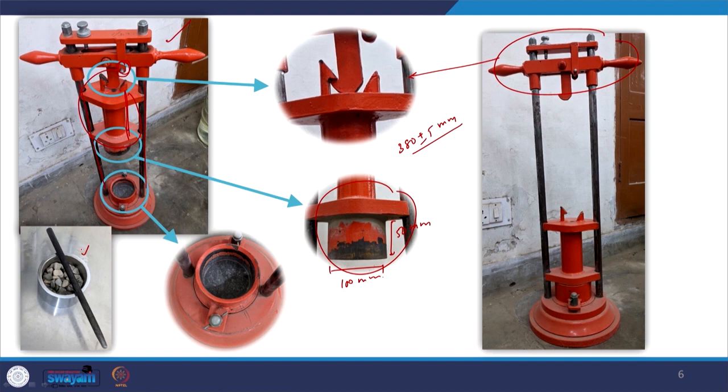The sample measure is 75 mm in dia and it is 50 mm in height, but this sample measure is not directly put in the equipment, alright. This sample measure is used to measure some amount of aggregates, and this aggregate is then placed in the case hardened bottom cylinder, alright. So, there is some difference.